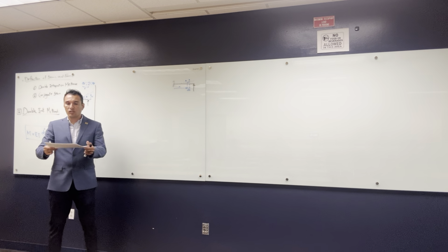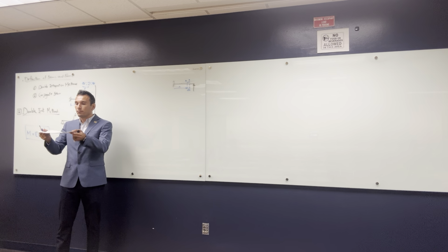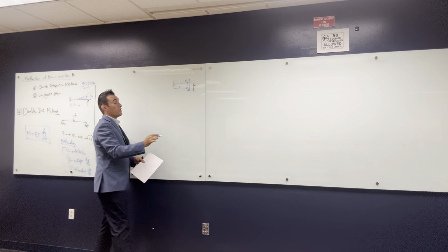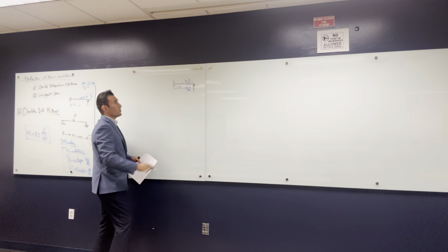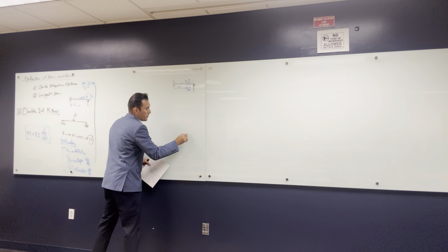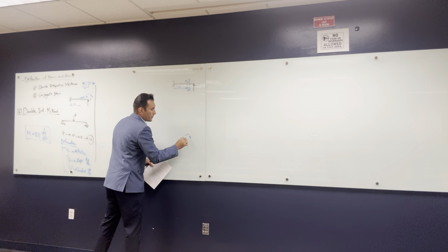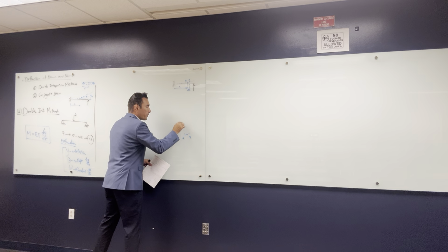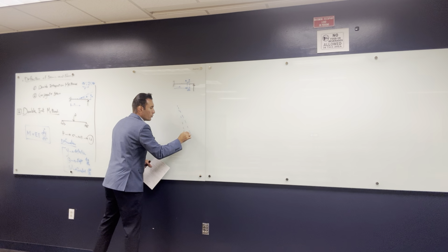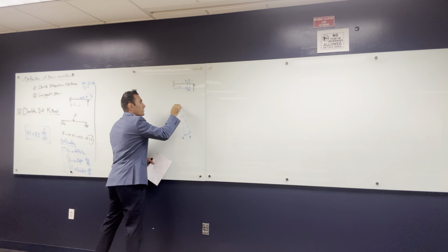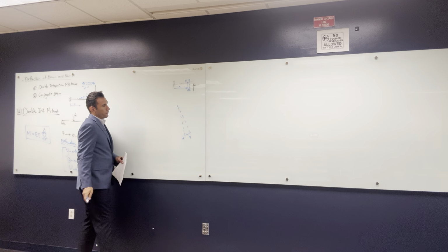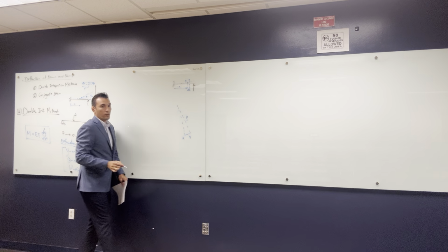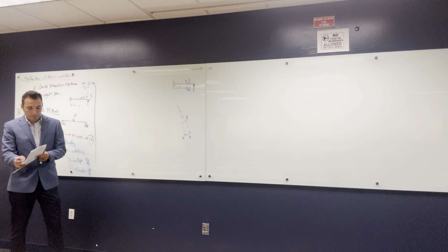When a beam starts to have a deflection, it's going to be like a curve, and this curve is part of a circle. To find the center of this circle, let's get AB here. This is A, and this is B. To find the circle that A and B are part of, you draw a perpendicular and another one until you get to the other point. This is the center of the circle that AB is a part of. We call the radius rho of this circle.